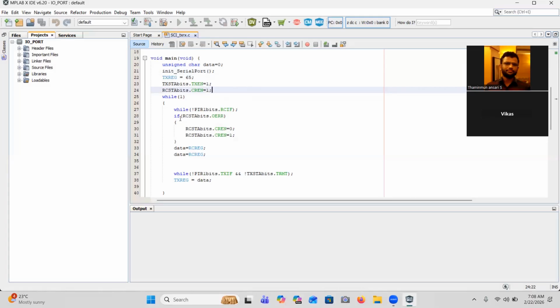We are polling, right? We are simply monitoring this particular bit. If that bit is 0, we are waiting. If it is 1, then we come and read the register. Right now, that is how we are doing it. So these two infinite waits, which represent polling methods, will consume many machine cycles. We are going to avoid that using a concept called interrupts.